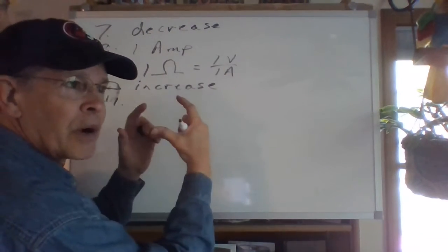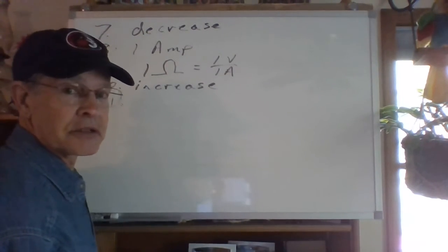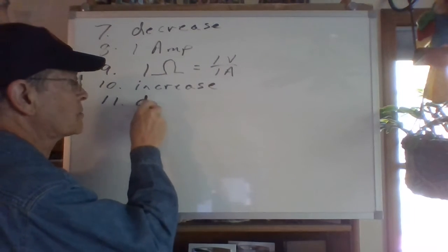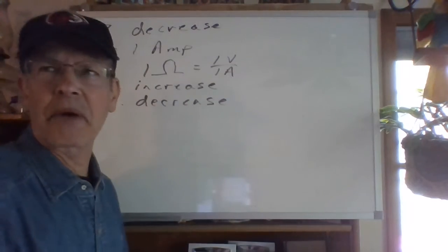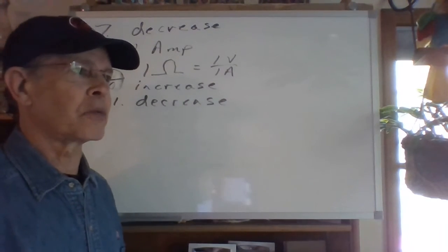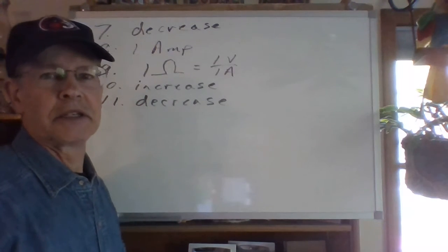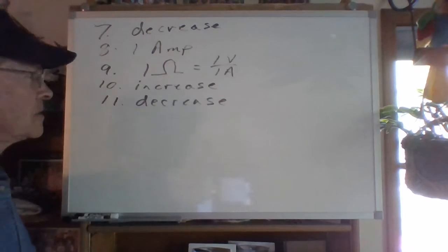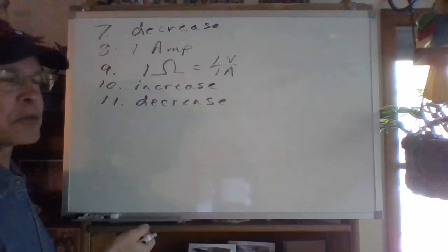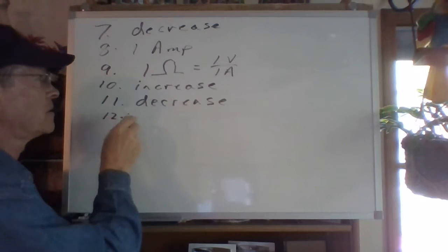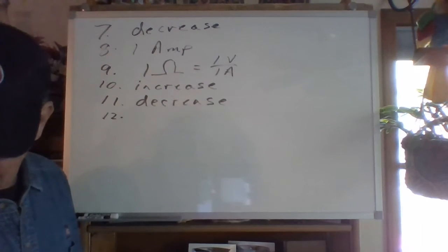Well, if you get a bigger wire, increased cross-sectional area, bigger wires decrease resistance. And that's why you would have to compensate. If you're going to go a long ways with an extension cord, or wiring in your home has to go a long ways from the breaker box, then you need a bigger wire for long distance. It decreases resistance to increase cross-sectional area, inversely proportional then, but length is directly proportional. Twice the length, twice the resistance.